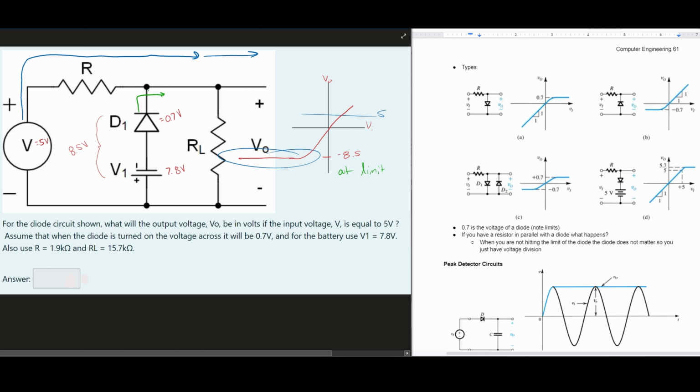it's going to act as an open circuit. If we draw this in green, we would just have this right here and this right here. Not like a capacitor, but we'll just draw it like this and draw 2 little nodes to symbolize an open circuit, and also write that it's open. Since it's acting like an open circuit, we just have this voltage, this resistance, and then the voltage output. It would be a little bit different if the arrow were pointing the other way, where we would be at 8.5.